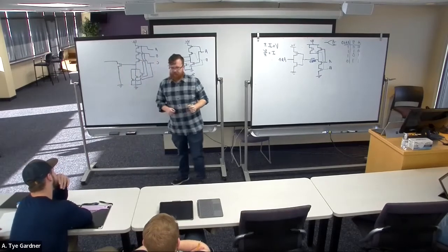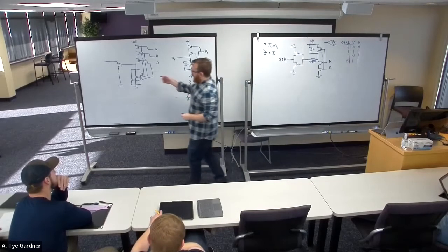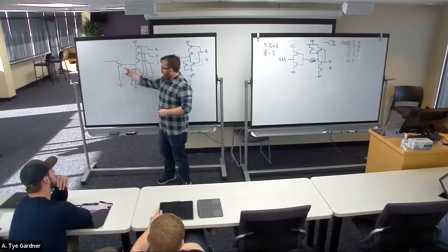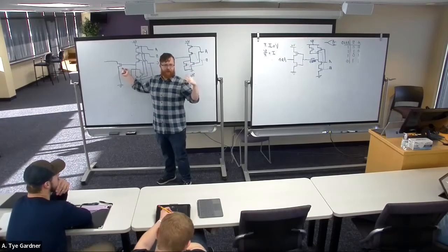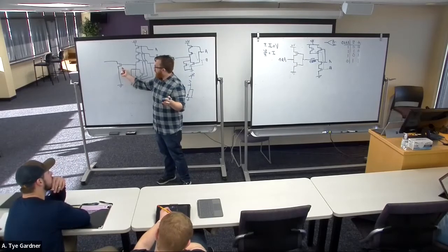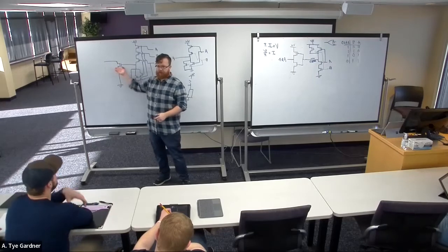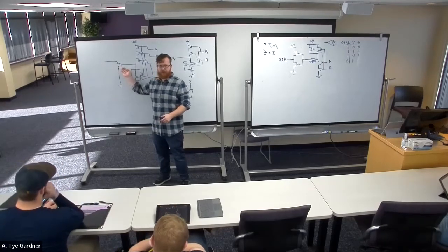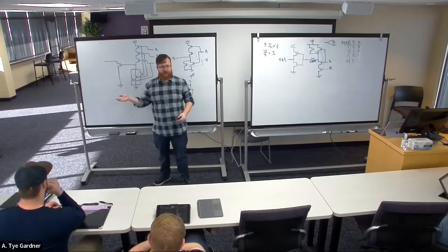I just do this. So now the output is sending into a gate. The gate has no input current; we're going to pretend that for the moment. And what that means is that this is decoupled or doesn't see the output. We've separated the output from the input because it's got this intermediate stage. This stage can make a 0, but it can't make a 1.